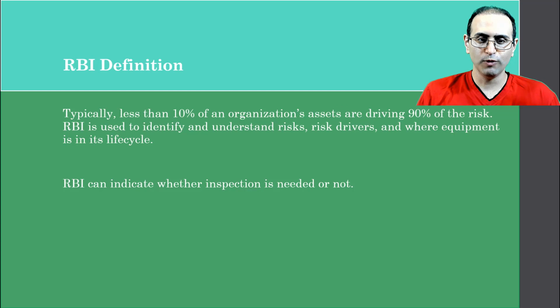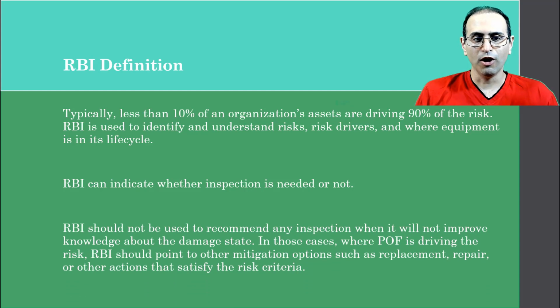RBI can indicate whether inspection is needed or not. In so many cases, you don't need to inspect everything. You may need to inspect a specific piece of equipment. If you do that, then you won't waste your money on inspecting other things that are basically safe at this point, and you don't need to do any sort of inspection or other tasks for them. RBI should not be used to recommend any inspection when it will not improve knowledge about the damage state. So if you don't need to do inspection, you should not waste your money. You should put that money into something else.